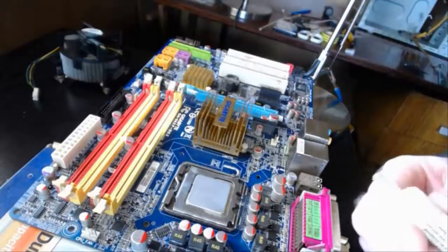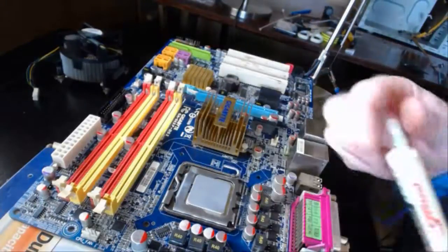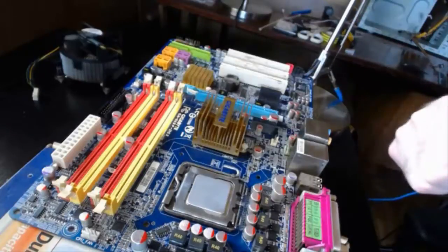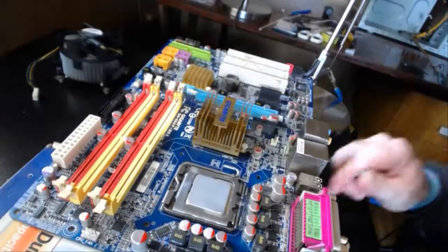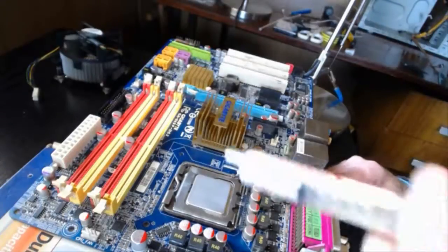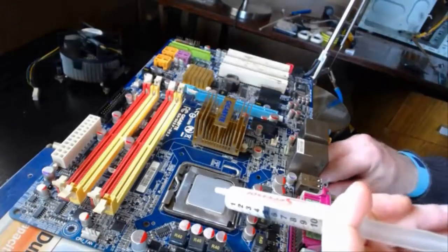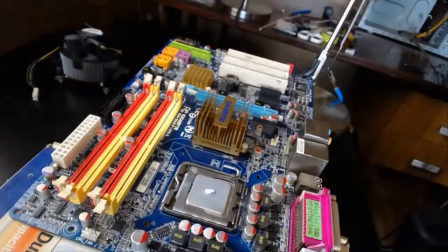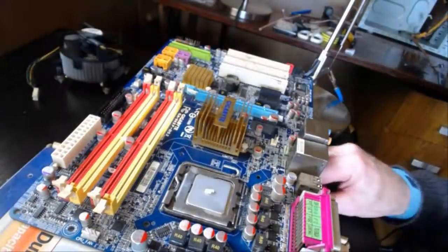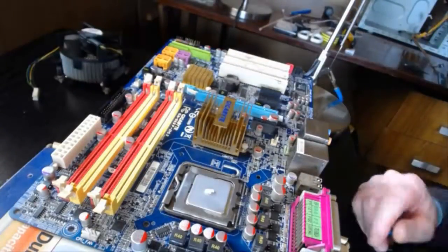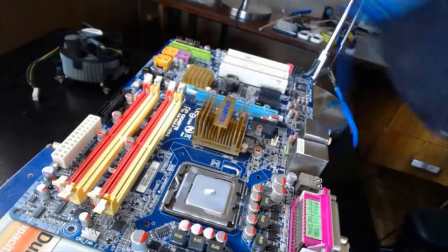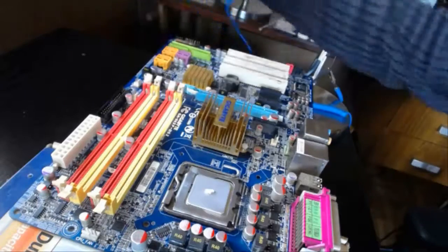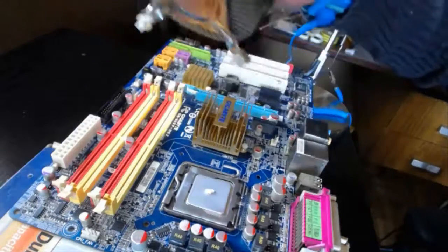You will need thermal paste. So you can get this at the store, or it may come with your fan. Now what you do is, you just drop about half the size of a small garden pea, and that's all it takes. Don't put any more on it, because it can get very messy when you're replacing the fan or the CPU next time. And then you just place your fan down on top of that.